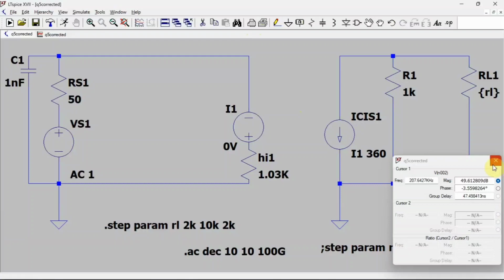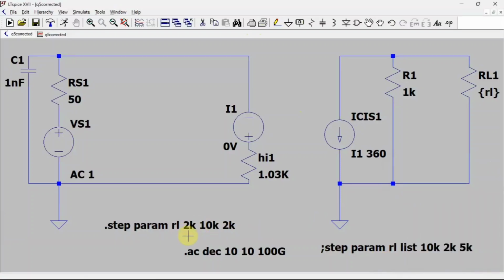Once again, the syntax is that you must give the initial value, then the final value, and here you give the step. Let's say you need to go from 3k to 9k in steps of 1k, that is 3k, 4k, 5k. You can give 3k here, 9k here, and 1k here. But let's say you need 3k, 6k, 9k, 12k, and so on. You give 3k here, 12k here, and 3k for the step. So: initial value, final value, and the step you take each time.